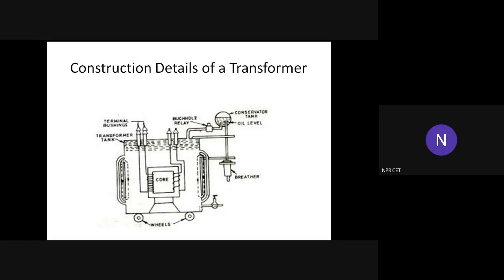It contains high acidity and more carbon, so they reduce the dielectric property of the oil. That kind of oil has to be removed by the drain valve of the transformer tank. The drain valve is fixed in the bottom side of the transformer tank, right?